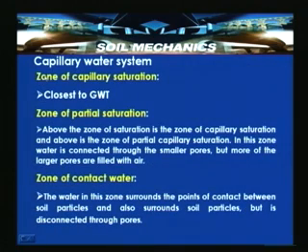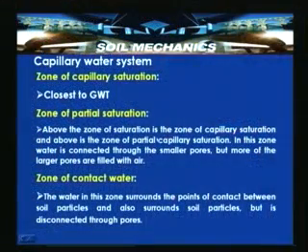Now let us look into the details, like the zone of capillary saturation, which is closest to the groundwater table, remains in contact with water, and has columns of water occupying the pore spaces of the soil, which results in saturation of the soil mass even above the groundwater table. So, above the zone of saturation is the zone of capillary saturation, and above that is the zone of partial capillary